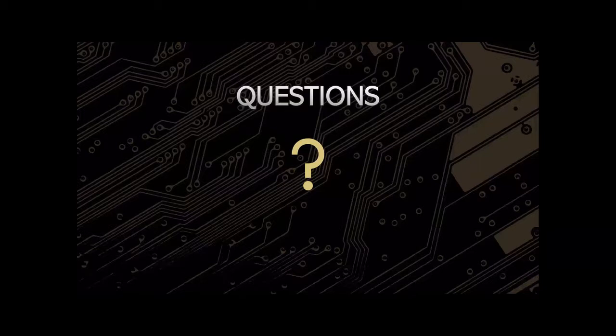Which brings us to the question of what files do you guys like to get? We like to see the Gerber 274X, and if not, then ODB++. We can run with those all day long. All right, do you guys pull in the IPC 2581 file format at all that you're aware of, Elijah? That I know of, no, that'd be something more on the sales side once they receive your Gerbers. Usually if it's something a little weird, they try to convert it before it comes to engineering.